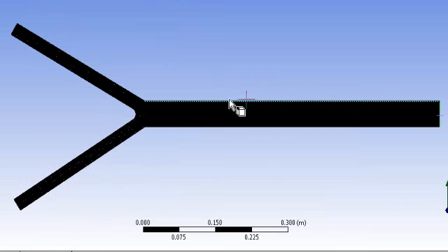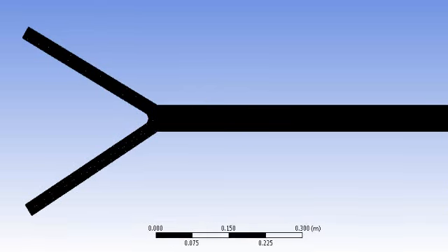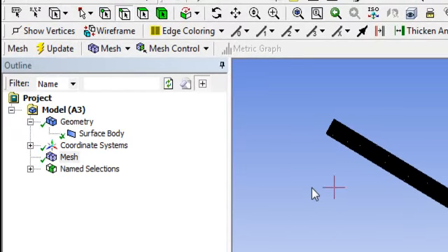You can specify these walls as mixing wall. You can specify these walls as hot water tube wall, whatever you want. But actually we don't need to define those walls because we don't have anything to calculate on those walls. So we will stick with a regular wall and update one more time.